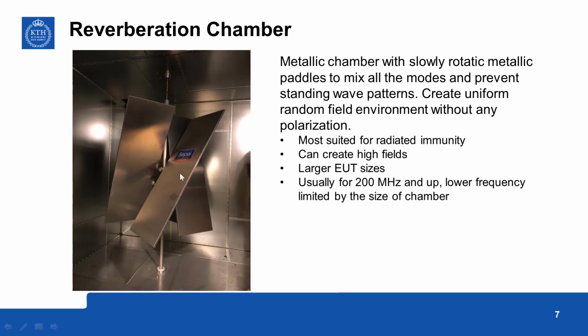Then another type of chamber is the reverberation chamber. This costs much less than an anechoic chamber. It is basically a metallic chamber with slowly rotating metal paddles to prevent standing wave patterns. So it is called mode mixing. So you can have multiple reflections from all the walls.